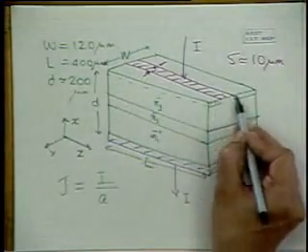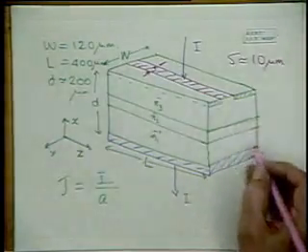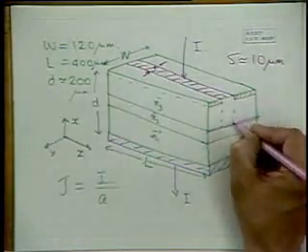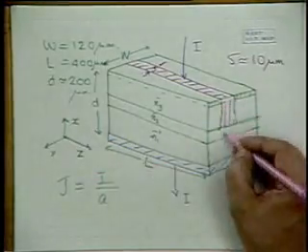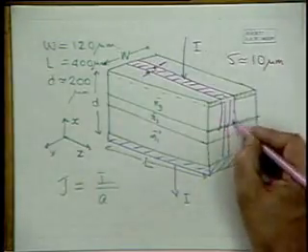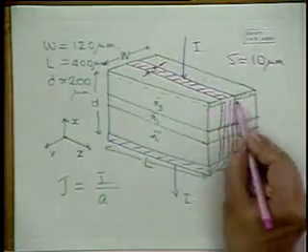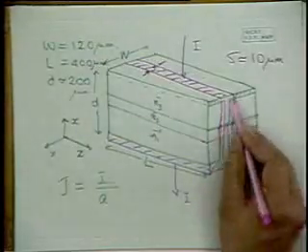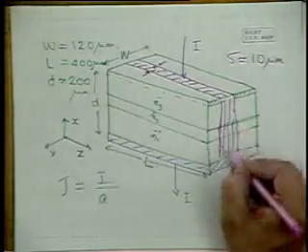This is an insulator, so current cannot flow, and as a result of this oxide, the current flow is mainly confined under the stripe, like that. Most of the region is outside this streamline, and where is the laser action taking place?